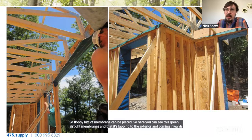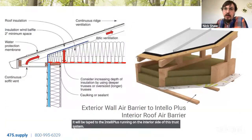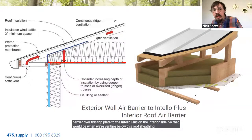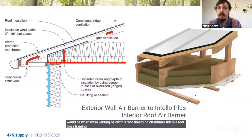So it will be taped to the Intello Plus running on the interior side of this truss system. And we're talking about this transition coming from your wall's exterior air barrier over this top plate to the Intello Plus on the interior side. So that would be when we're venting below this roof sheathing. Oftentimes this is a roof truss framing, and maybe not site cut rafters.